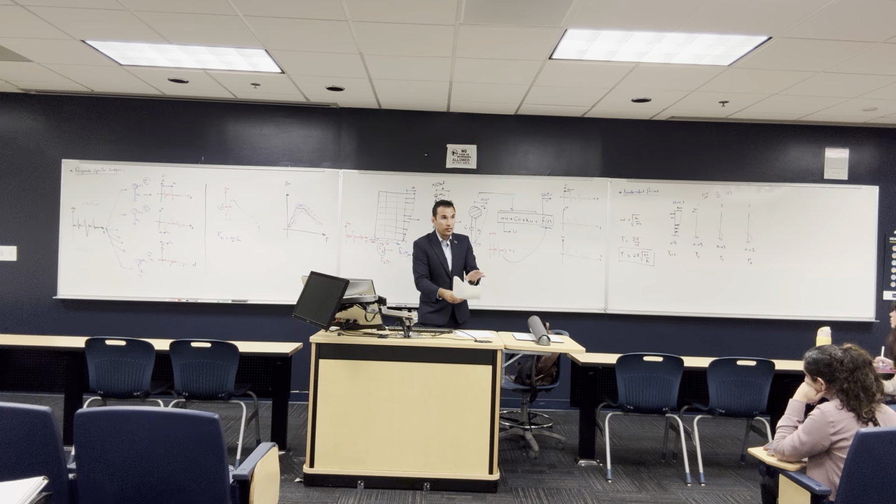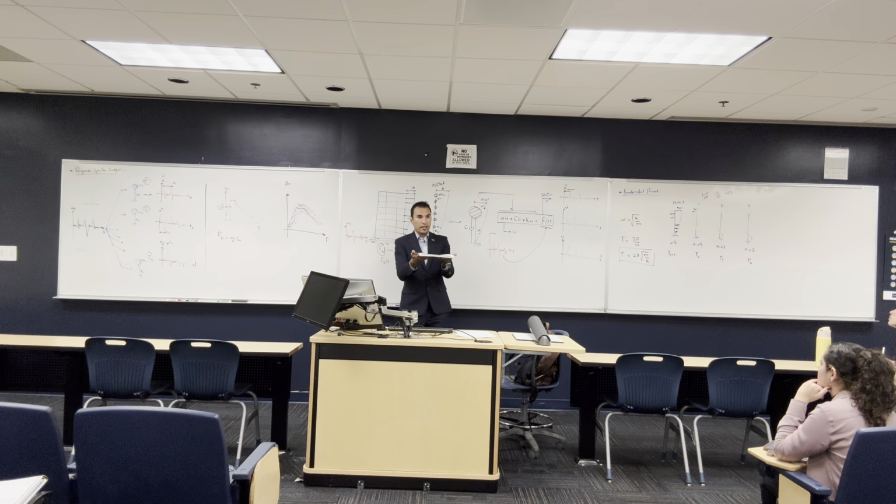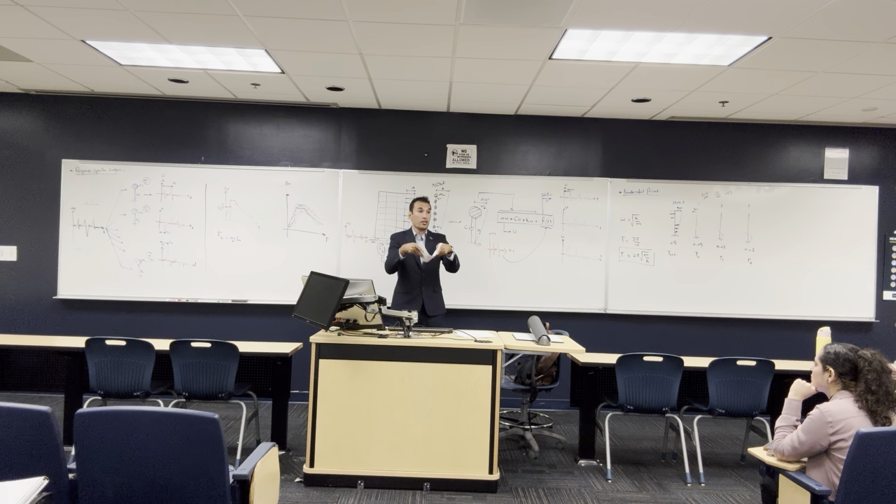Bending moments, have you guys heard about bending moments before? In what class? Mechanics of materials. So a bending moment is like if you have a cross section like this and it's gonna bend. Bending moment is the enemy of the structural engineer. We don't love bending moments because bending moments are sneaky. They make tension and compression at the same time.